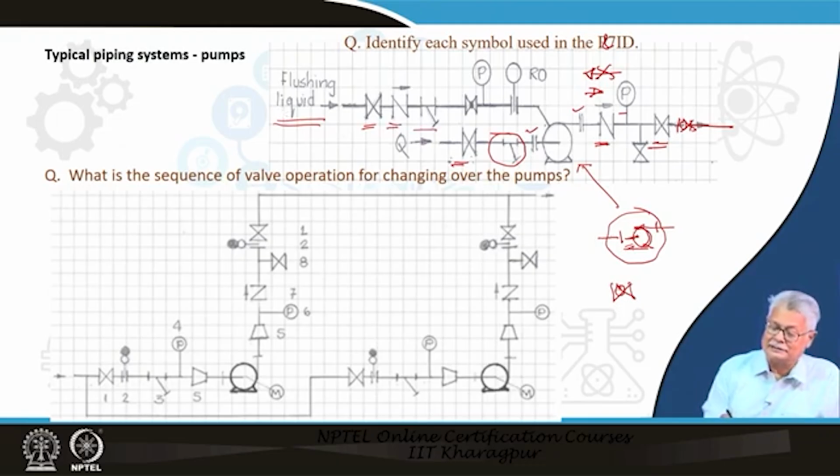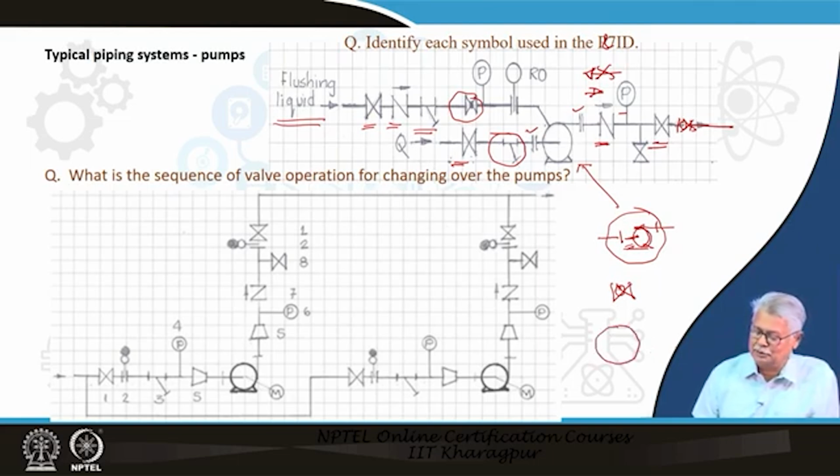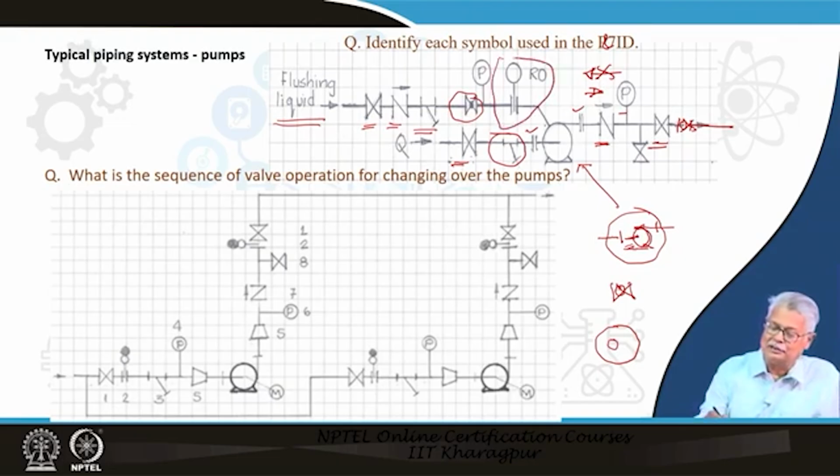You must have in fact another strainer here, and to regulate the flow you have a globe valve here, followed by a pressure gauge and a restriction orifice. And a restriction orifice, what does it do? A restriction orifice is nothing but a flange. It is a disc with a hole inside. The purpose of the restriction orifice here is to provide pressure drop.